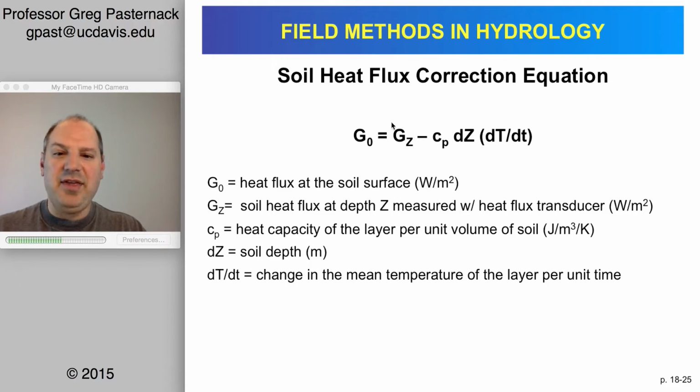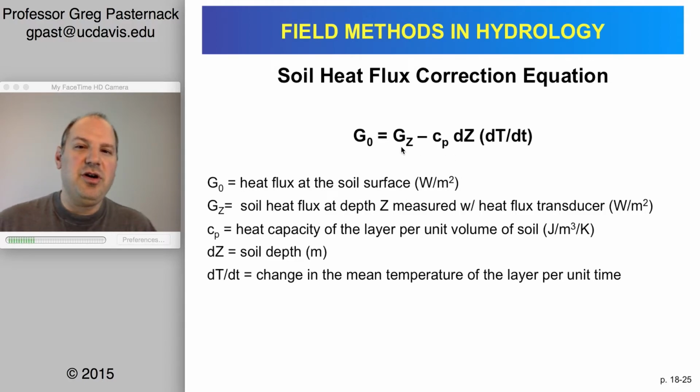And so you can see we have the heat flux plate, we've got one or two temperature sensors, and then the heat capacity you can just get from a textbook or the internet or whatever. So it's a relatively simple thing to measure, but in terms of doing it well and accurately, like most things in the soil, it turns out to be fairly hard and problematic and discouraging. Well, isn't that true of all of hydrology?